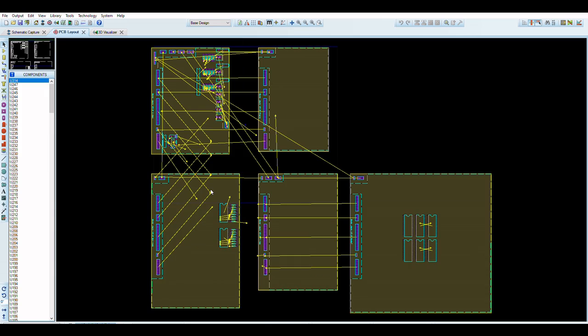I also wanted to make sure that the auto placer understood that I wanted a nice balance on the board, in terms of placing the components for one half of the Sprite logic and then the other half of the Sprite logic. Because when the Sprite logic renders, it actually renders alternate scan lines as it's outputting the pixels to the output video.